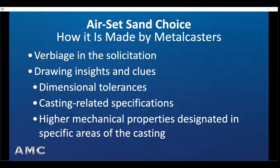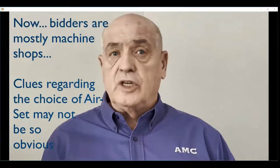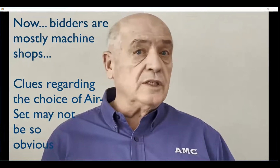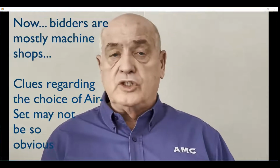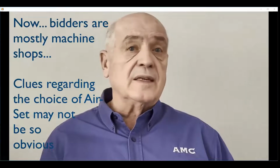Because of its tolerance capability, cosmetic appearance advantages, and/or its ability to achieve higher mechanical properties in areas designated as such on the drawing, the sand metal caster would choose the air-set sand process. Now, as bidders are most likely machine shops, the subtleties in the solicitation, especially the drawing, may not be so obvious to a cold start machine shop new awardee. Those subtleties have to be investigated, and that takes time.